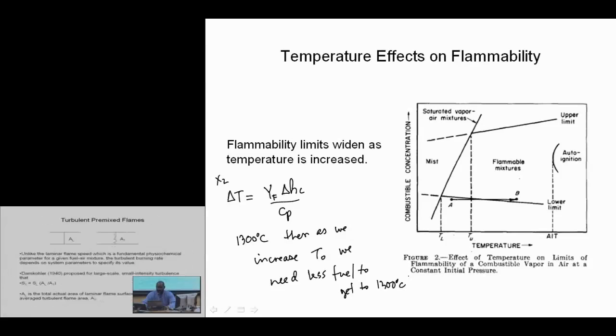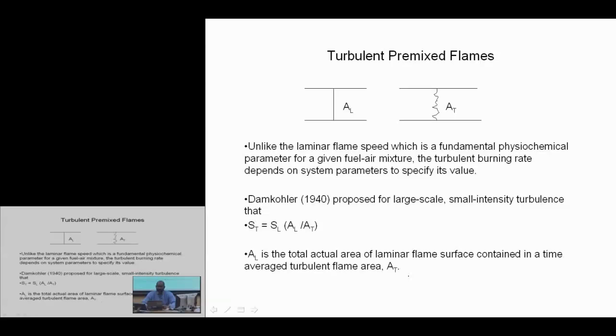Okay. One last thing. Turbulent premixed flames. We never talked about turbulence. Turbulent premixed flames are not as important for fire issues as they are for engine applications, whether gas turbine or internal combustion engines. One area where it is important, particularly in the nuclear area, is if you had a hydrogen leak, premixed with air, and you get this propagation process initiated. There's a spark, and you get a laminar flame initially.